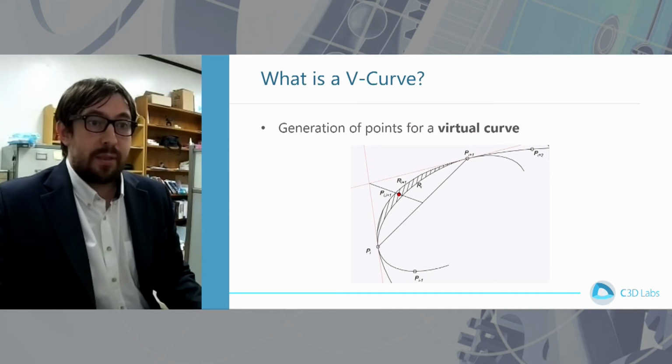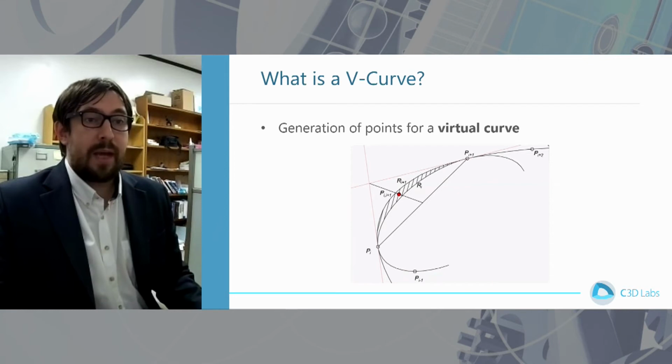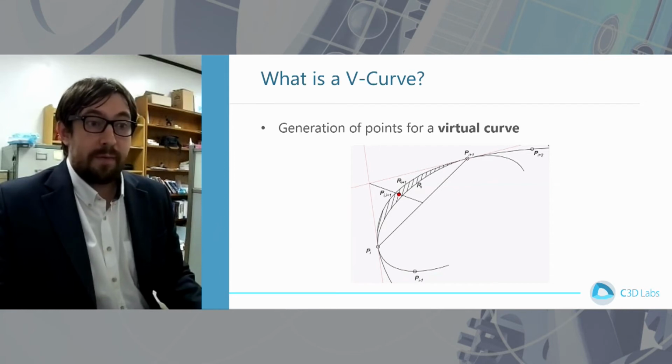The second innovation is the algorithm that generates the virtual curve, or V-curve, on the basis of a spline constructed with a discrete set of double osculating conic curves. We developed the V-curve method with some notable features. The first is that it offers the lowest number of curvature extreme values. The second, it exhibits duality because the V-curve can be defined both with base vertices and tangents, just like conic curves.